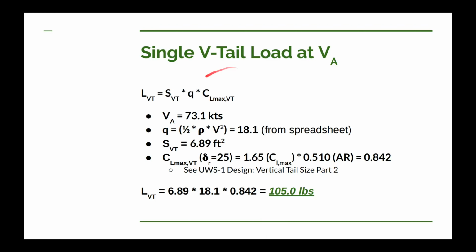Well, now it's time to plug in a whole bunch of values and figure out what that single vertical tail load is at our maneuvering speed. Now this equation, most of you should be able to recognize. This is our lift equation. We've used it in a whole bunch of videos. You have lift on this side, surface area on this side, dynamic pressure here, and your coefficient of lift here. So we've used this on just about every flying surface doing calculations on either surface area or lift.